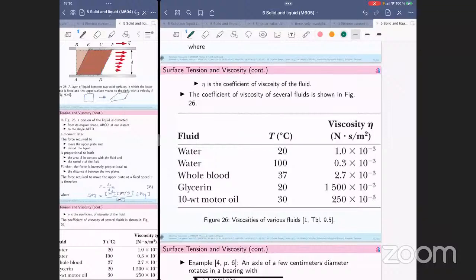Okay. If none of you would deliver the answer, I would say it's because the heat you give to the molecules of that liquid will break down, reduce the attractive force inside that substance. So when there is less attractive force inside that substance, the viscosity is going to be lower, because there is lower friction, right?